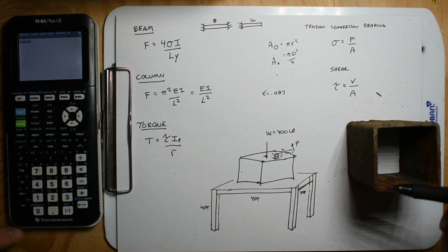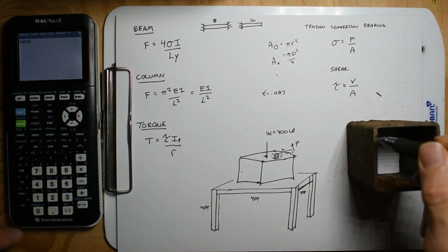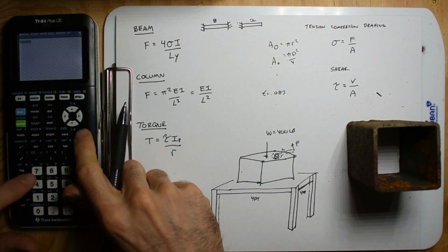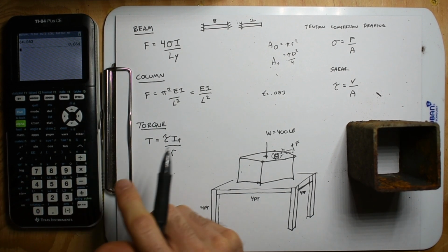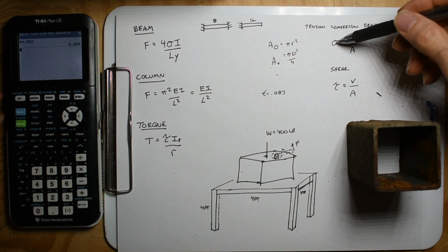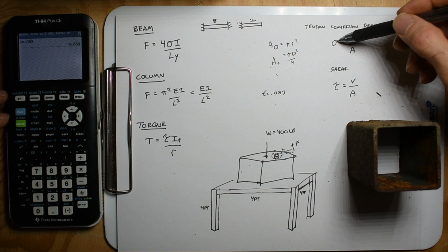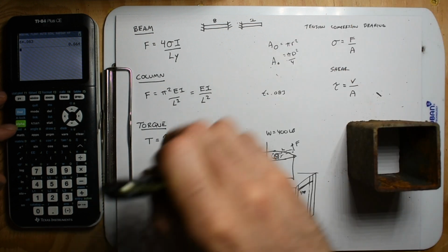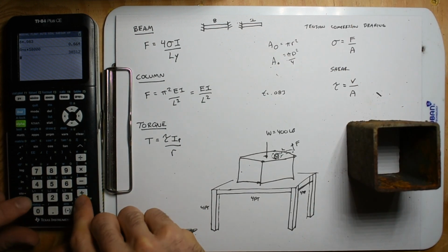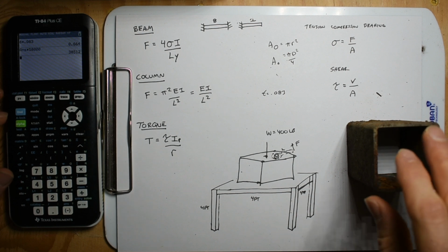0.083. And so we have, well, what's the perimeter? This is 2 inches, so we got 8 inches. So we got 8 times 0.083, so that's the area. Strength times area, because strength is in pounds per inch squared. So 58,000 pounds per inch squared, multiplied by that area. And we get a force right off the bat of 38,000.